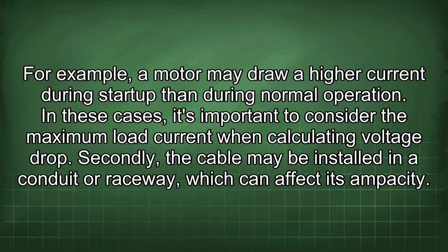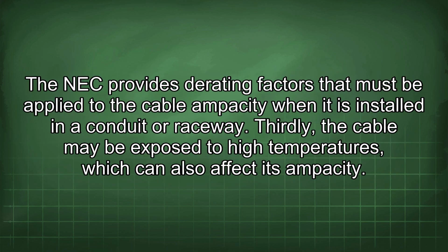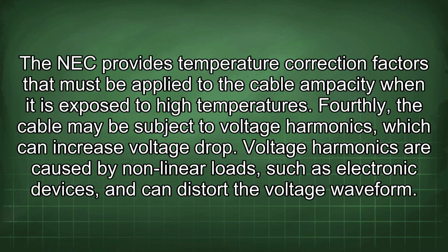Secondly, the cable may be installed in a conduit or raceway, which can affect its ampacity. The NEC provides derating factors that must be applied to the cable ampacity when it is installed in a conduit or raceway. Thirdly, the cable may be exposed to high temperatures, which can also affect its ampacity. The NEC provides temperature correction factors that must be applied to the cable ampacity when it is exposed to high temperatures.